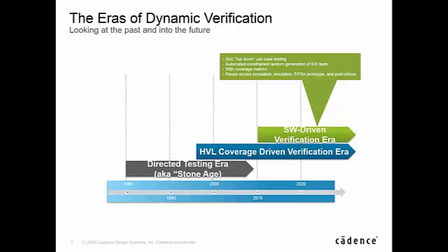And so this is the era that we refer to as the software-driven verification era, looking at SOC top-down use case level testing, and automated constrained random generation of software tests, obviously maintaining what we've learned from the value of coverage metrics and wanting to apply coverage metrics at this SOC and system level, and then the ability to reuse all of those tests across the many platforms that have to be utilized during the process, from simulation, emulation, prototyping into post-silicon, as we've been talking about.